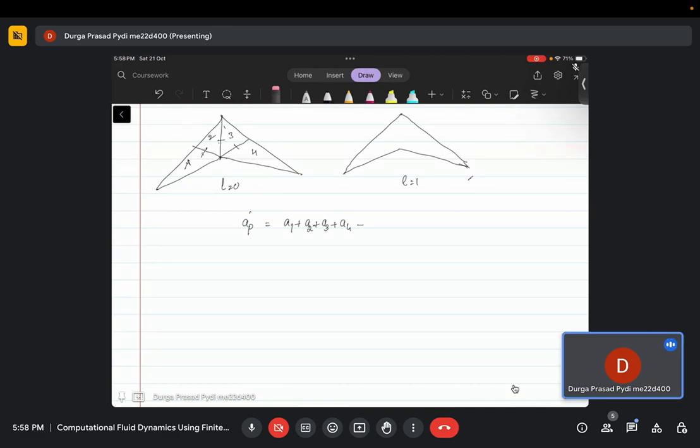So then we need to essentially subtract those components. So you have some A12. A12 is essentially the diagonal, the A east or A west term corresponding when you are writing for the A1 cell, and similarly you will have the same in your second one as well. So you have to subtract A21 as well. A21 is essentially the equation you will be writing for the second cell. Similarly you will do for the other ones as well. So you have A23, A32, and for the last one A34 and A43.